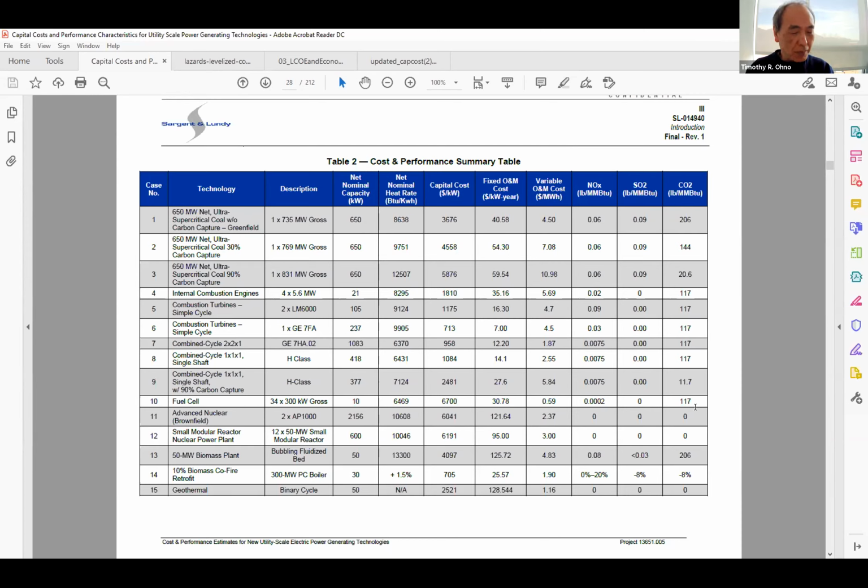And again, maybe that makes some sense because in the coal, I'm managing a solid medium. I have to pulverize it. So I've got a train that comes in with chunks of coal. I have to send it through a pulverizer. So now I've got a pulverizer stage. I probably have dust bags and all sorts of other things to manage pieces around that. As you can see how that could be pretty expensive. In the case of natural gas, I have a tank of natural gas and I connect it to the system and it runs. So capital costs are significantly different.